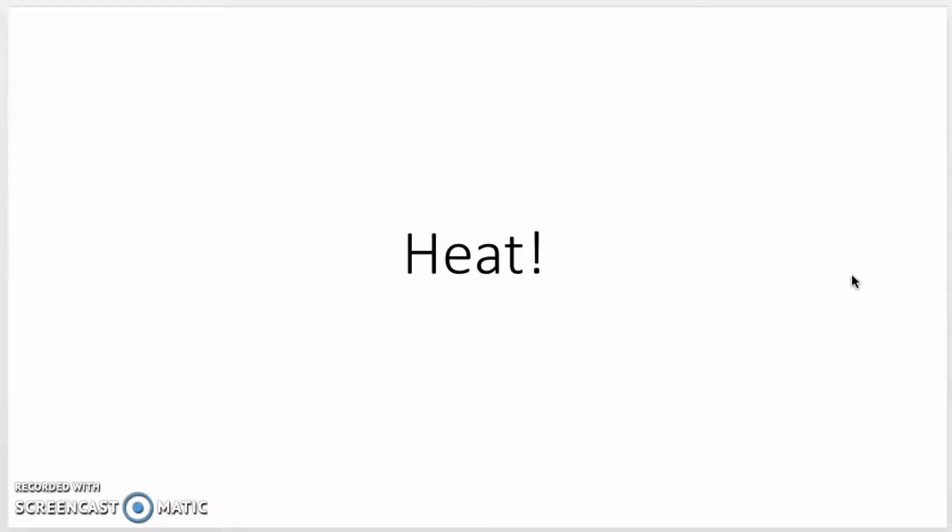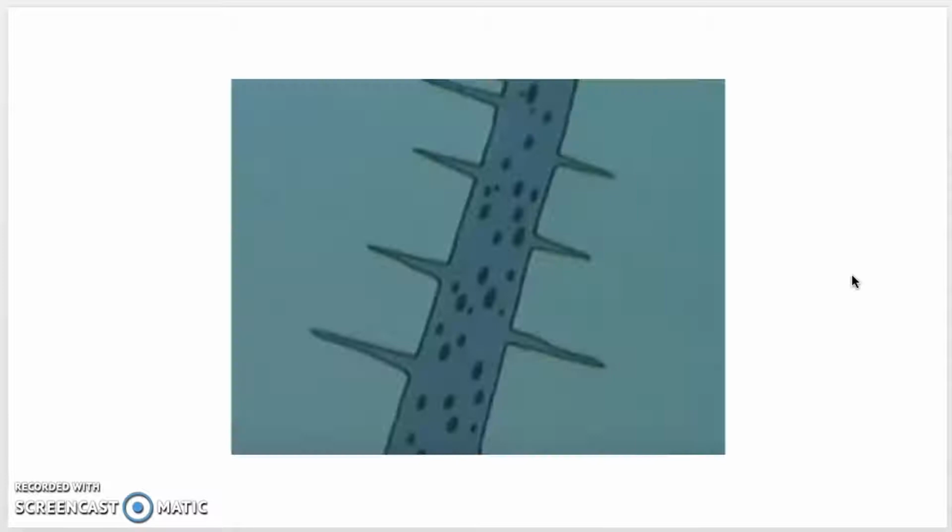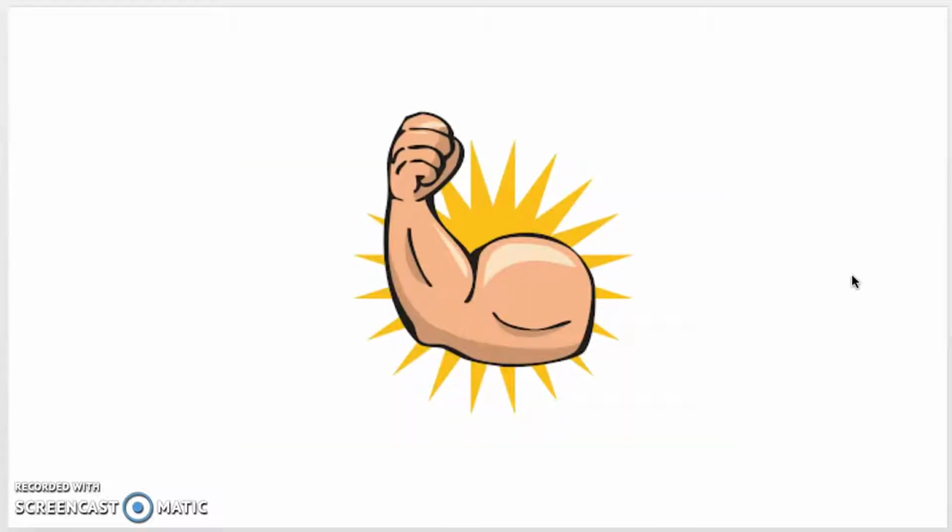So we're going to heat our piece of steel back up, and then let it cool slower this time, and then we'll get carbon within these needles, and basically this will restore some of the ductility and reduce the brittleness of that steel, keeping it very strong, but reducing the brittleness of the material.